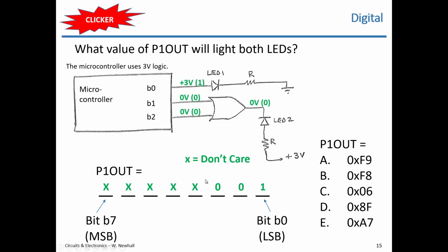least significant bits. So if I look at 4 bits at a time, and specifically the right 4 bits because those are the ones that count here, I need a 1 in this least significant bit. So what could this nibble, this 4-bit word, be? Well, it could either be 0, 0, 0, 1, which is a 1, or 1, 0, 0, 1, which is a 9. So the rightmost 4-bit word, the nibble of the byte, has to be either a 1 or a 9.